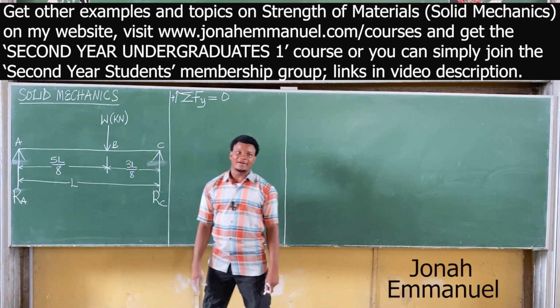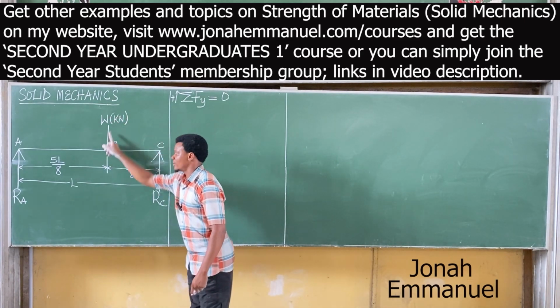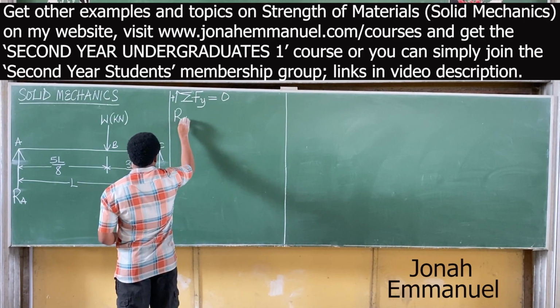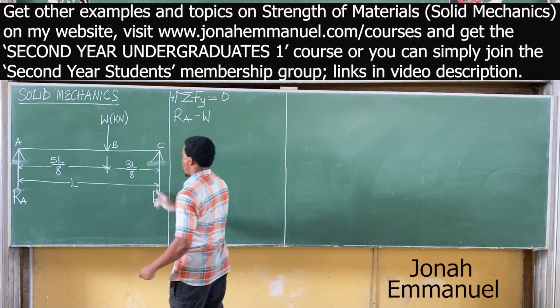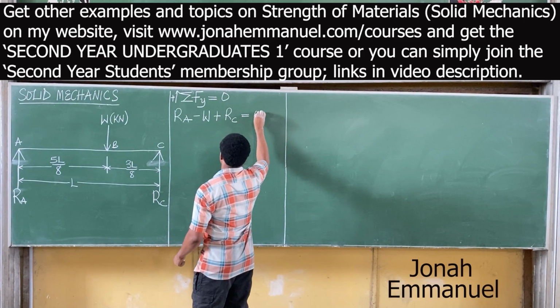How many forces do I have here? 3. You have RA going upwards, you have W coming downwards, you have RC going upwards. This man is going upwards, it becomes positive. So I have positive RA. This man is coming downward, it becomes what there? Negative. I'm having minus W. This man is going upward, becomes what there? Positive RC. It's equal to 0.